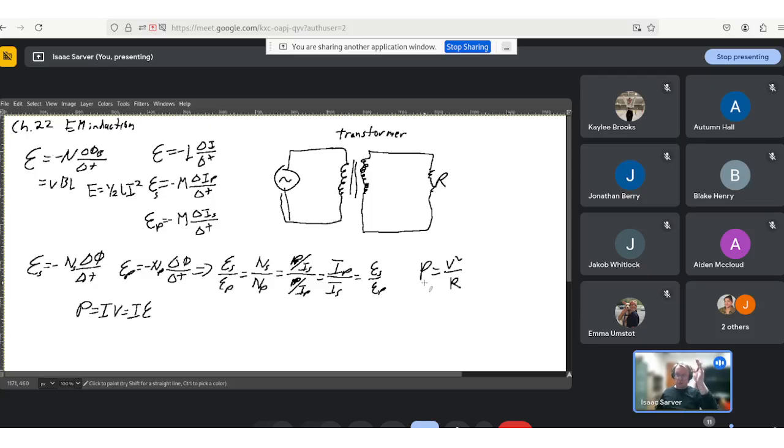In order to do that well, you had to step your voltage way up. Back in that day, in order to exchange your voltage and current, you needed a transformer. And transformers only work if your current is changing and your magnetic fields are changing. And so that's why AC works. If you have a DC circuit, it doesn't work.